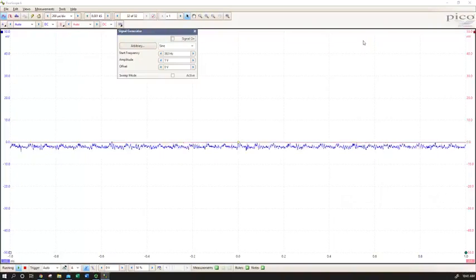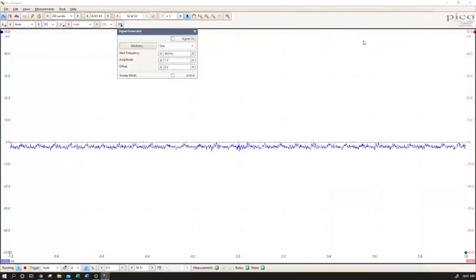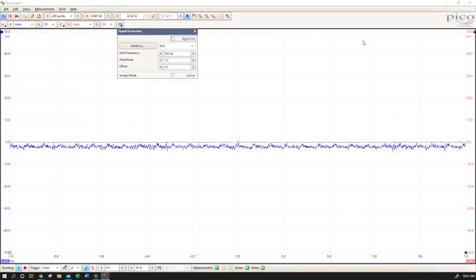You could see, in fact, on our frequency scans that the high frequency side was much broader than the low frequency. There could very well be a significant amount of resistance, and in fact, in the case of the audio transformer, I actually measured a reasonably high resistance. I think it was something around 70 ohms. So that's a very imperfect inductor.